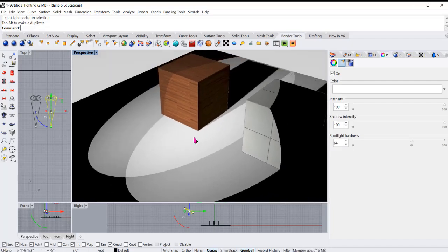shadows. I will say most of the time we're gonna have more than one light source when we have our models. However, if you want every single light to cast shadows, that's gonna take a lot of time to complete a rendering. So my recommendation is to have a minimum number of lights casting shadows. Meaning, if you have 10 lights, maybe some of them are just to generate the lighting effect, but maybe only 1 or 2 are the ones producing shadows.